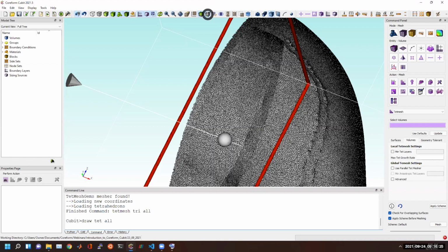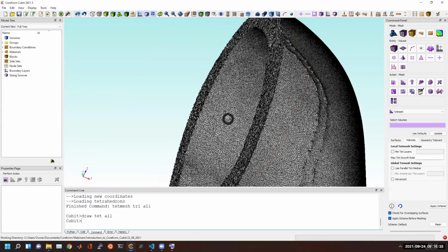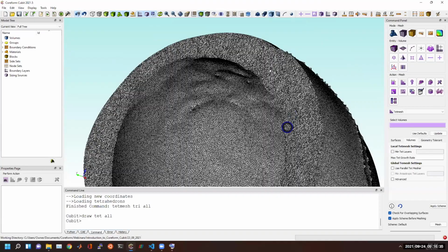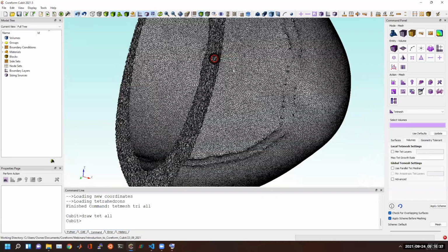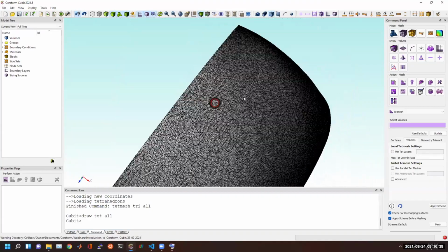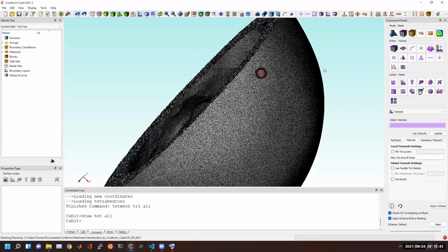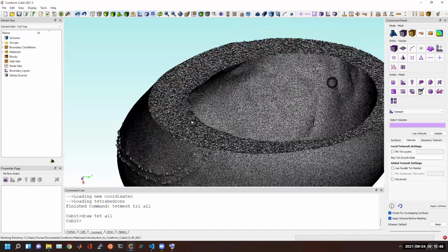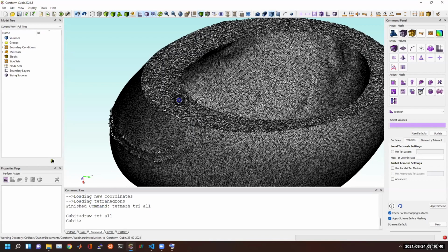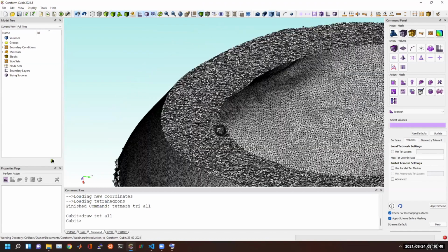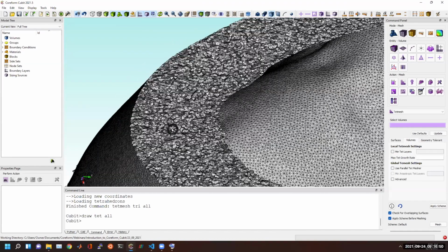So let's take a few seconds to render all these tetrahedra. While that's rendering, we had another question, someone who came in a bit late. What was the purpose of disassociating the mesh from the volume then, Greg? Yeah, so the purpose for this case is that if you have a good input triangulation, or if it's difficult to build a better triangulation, you can just directly build a tet mesh from those triangles.